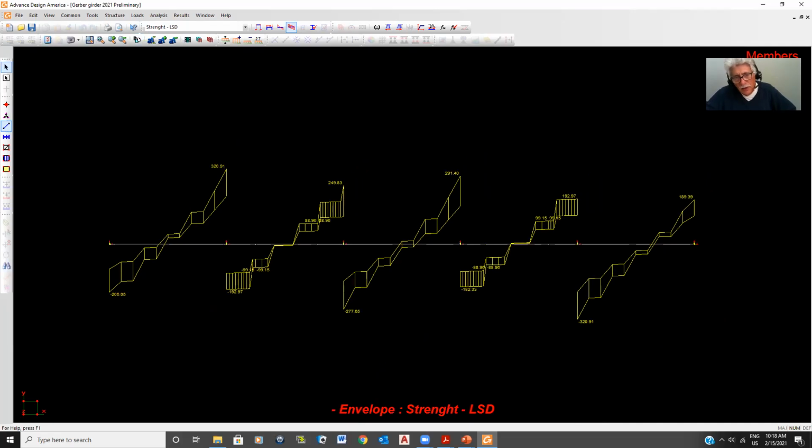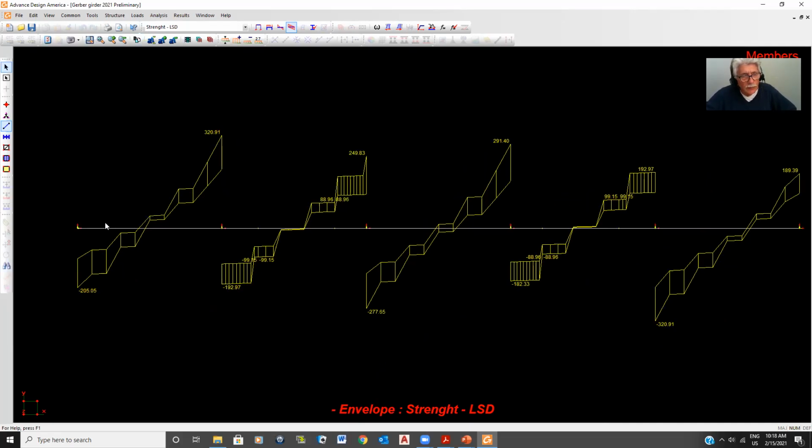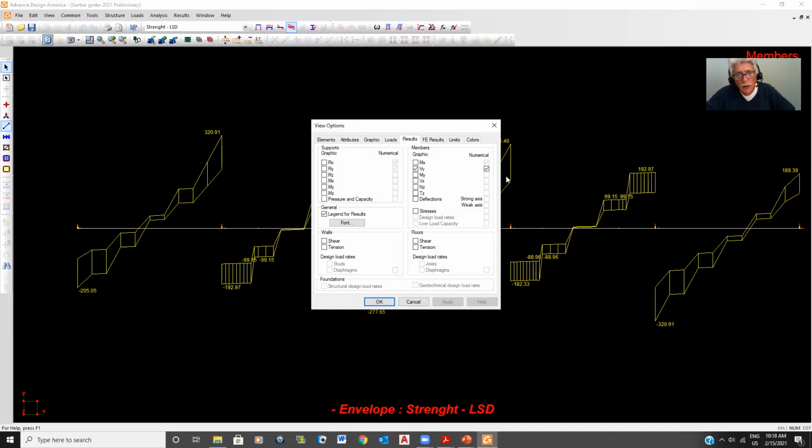Now, you'll see in the PowerPoint, in other words, this beam here has a maximum shear of 320.9 kilonewtons, okay? And then this is the overhang. So this is the shear for the overhang, or the suspended one, and this is the shear for the double cantilever. So when I'm talking about the double cantilever, I'm talking about this. So this is the maximum shear. So that's where I get my shear VF values for my design. And then ultimately, what I'm really interested in, of course, is my MX values, okay?